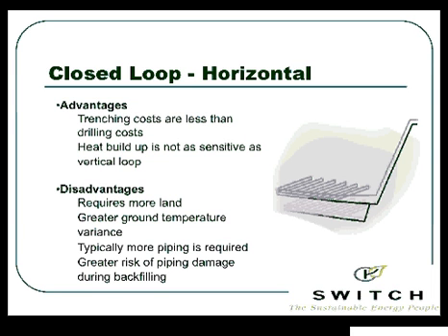I heard that with this geothermal system, the existing ductwork in the basement from an oil furnace is not sufficient. That's what I mentioned earlier. You're dealing with a cooler supply temperature, so we actually need to supply more of that air. So that ductwork, if you're doing a retrofit, might need to be changed. It depends on your house.